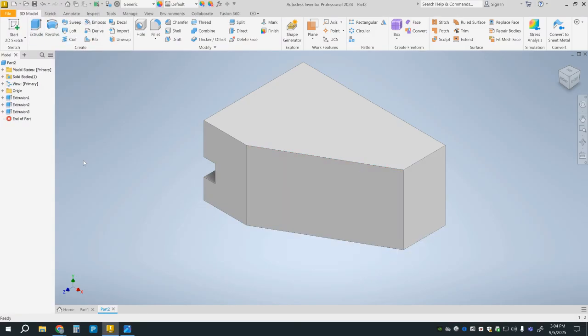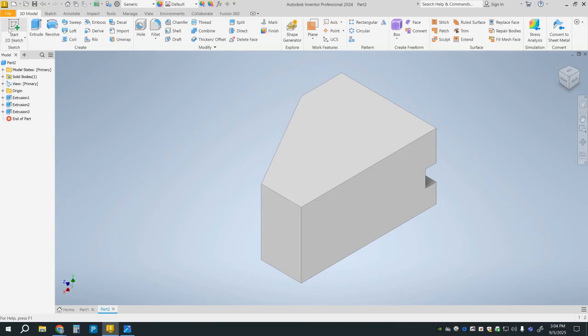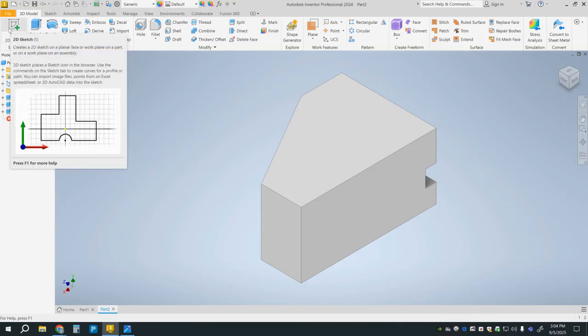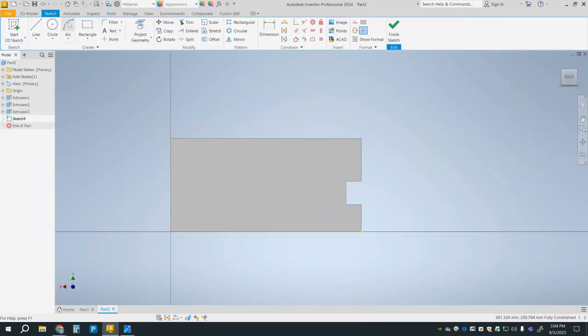I'm then going to do something very similar with the other part, this back portion over here. So I'm going to start a sketch on this back portion. I'm going to go over 90 millimeters. And then I'm going to make sure it snaps to this line here. Always avoid these little green dots. So I'm going to snap right there. And the dimension of this portion from this dot to the bottom horizontal line here is going to be 25 millimeters.